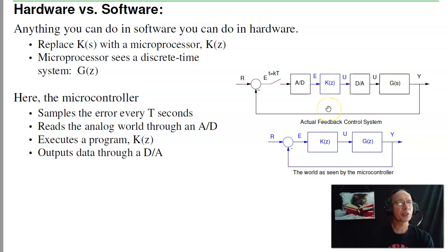Laplace transforms describe RLC circuits. A capacitor is an integrator, I equals C dV/dt. Inductors are differentiators, V is L di/dt. So any circuit that has capacitors and inductors is described by differential equations. Likewise, you use Laplace transforms.